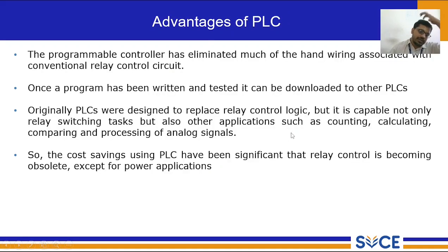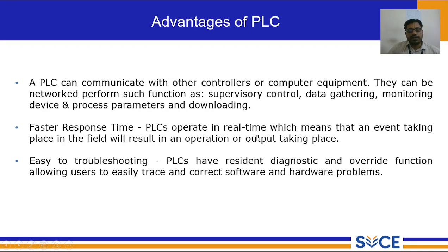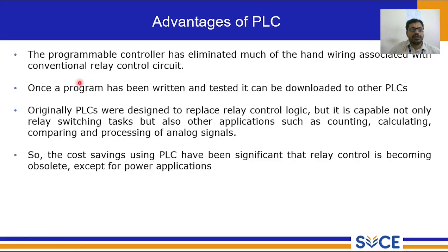Different advantages are there when we are using a PLC. A few are given here. The programmable controller has eliminated much of the hand wiring associated with conventional relay control circuits. You might have come across relay circuits. It is a very difficult circuit to replicate.